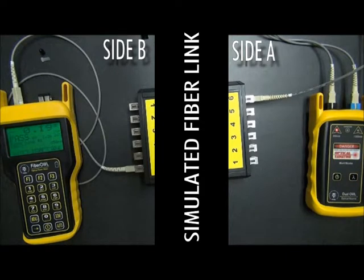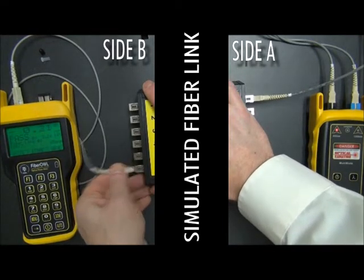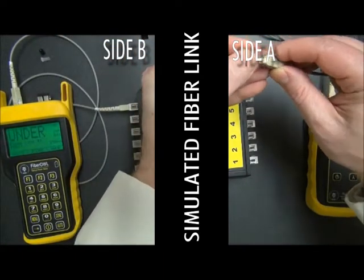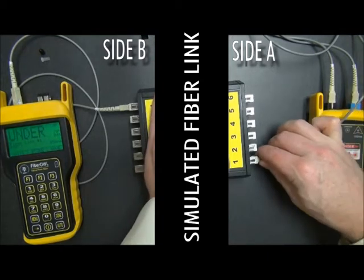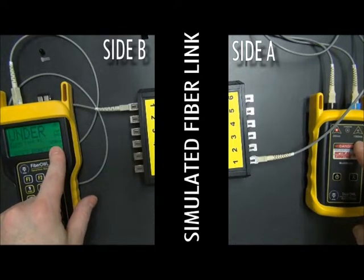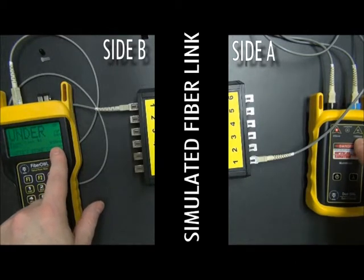Now, we've stored all the readings for all 6 fibers in this fiber link, but now we need to test at 1300. We will still use the same test cable over here, so we just plug the power meter cable back into port number 1. But now we take the 1300 nanometer patch cable and plug it into port number 1. Now, as you can see, it says under here, and that is because we're set to 850 here, and we still have the 850 nanometer LED lit. We need the 1300 lit.